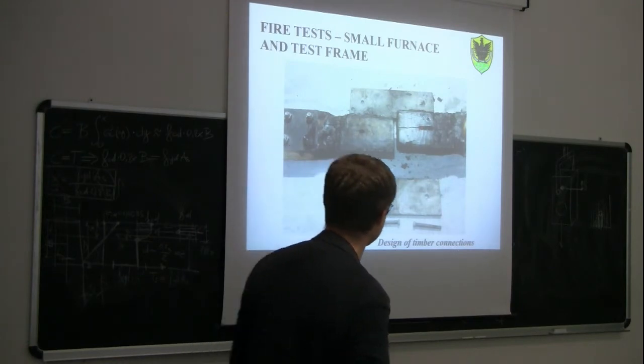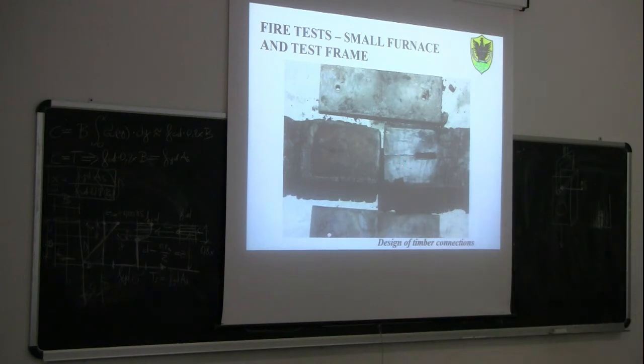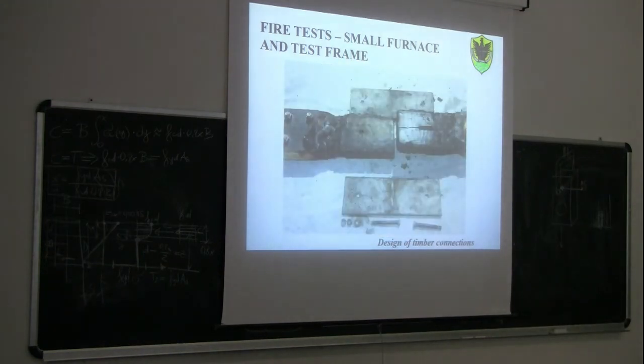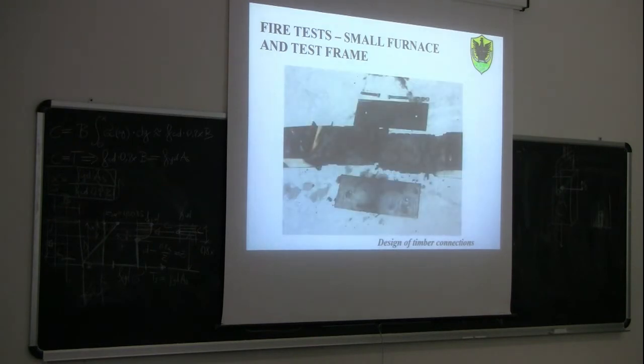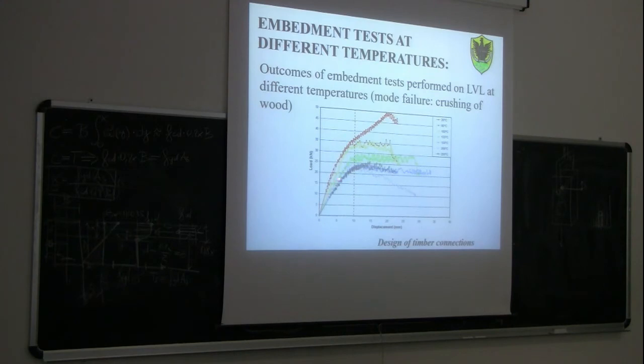Again, another enlargement of the hole. In this case, again, as you can see, if you have embedment, you have a failure which is quite ductile. Look at this color. We have certainly good ductility of the material. So in this case, we can certainly apply the lower bound theorem.